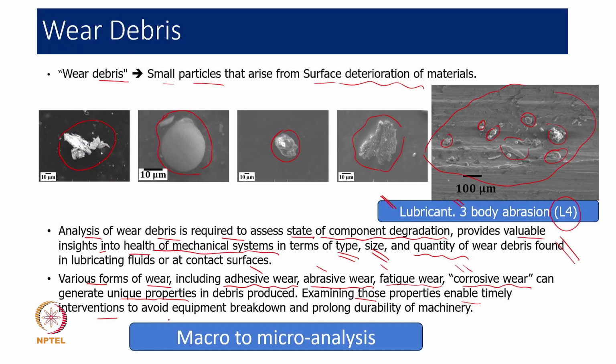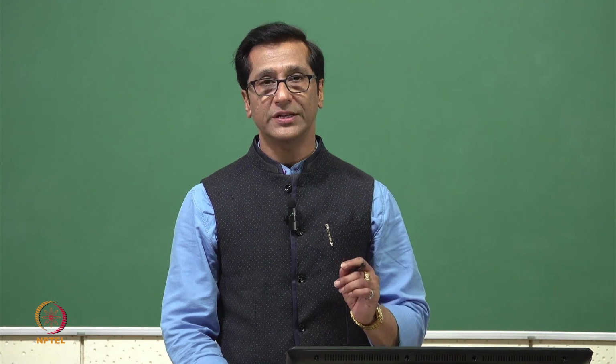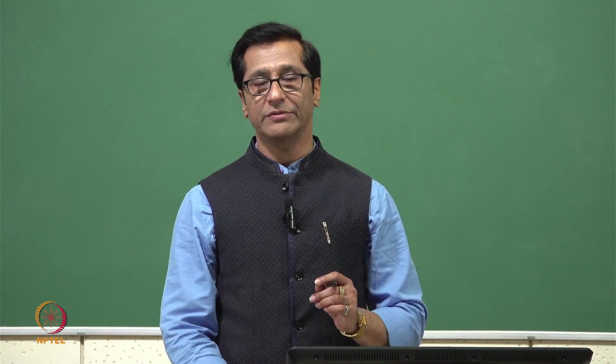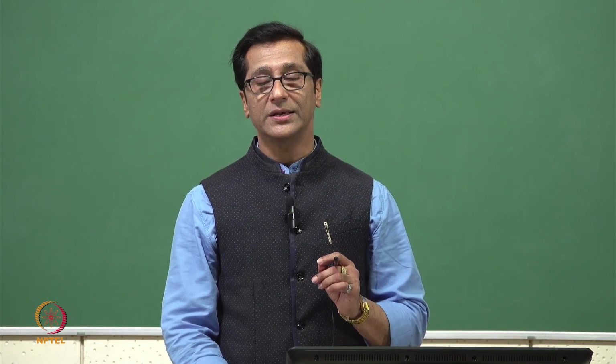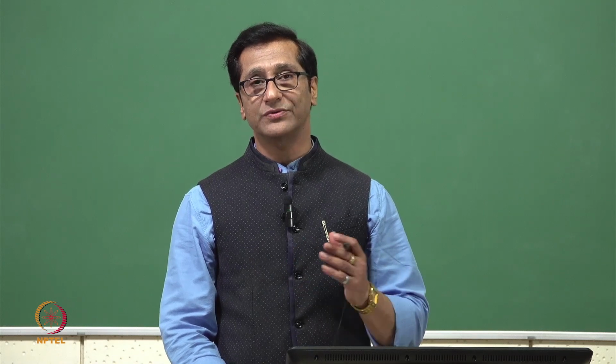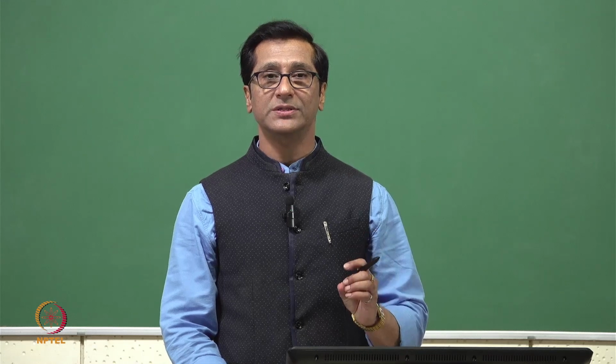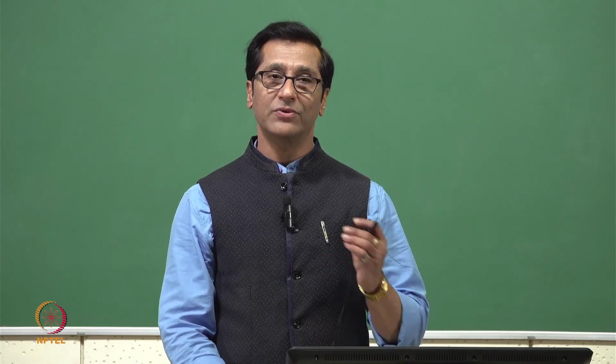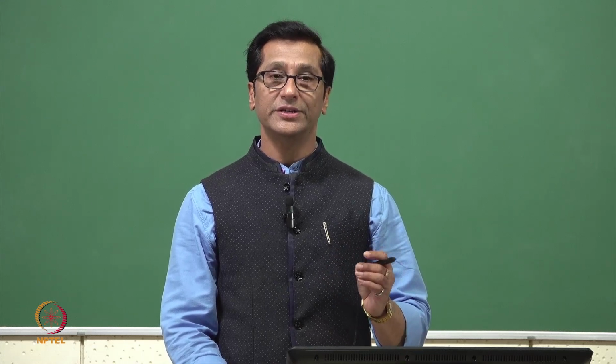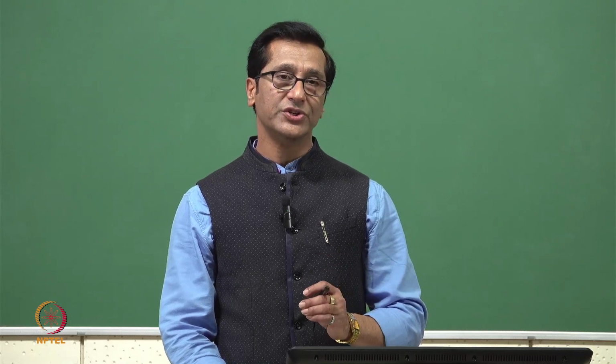Here again we are going from macro analysis to micro analysis when we talk about wear debris analysis, because mostly the wear debris will be at the micron level. Instead of the whole surface getting damaged, we are able to figure out initially that there is some chance of failure, that some fault has been initiated, and we should take corrective action.